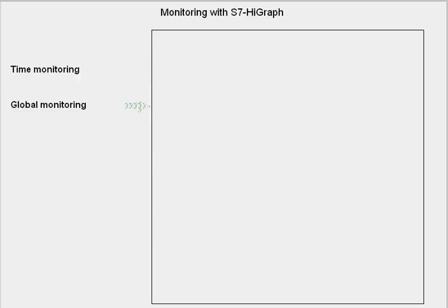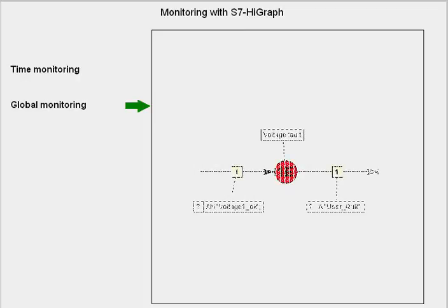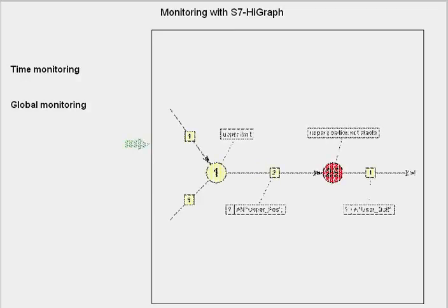With global monitoring, regardless of the actual active state, a signal is monitored constantly or globally for its state. In the program, this means that in any transition with conditions, state-dependent monitoring is when a signal is to be monitored only when it is in a particular state.